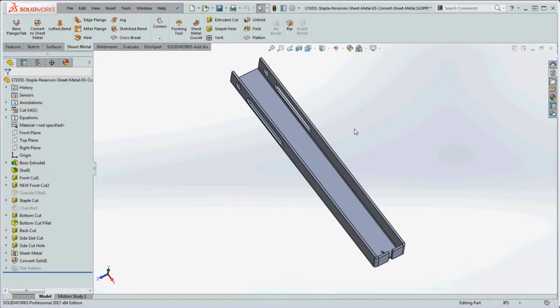You put your cuts, you cut it out, you put in your cuts for other items in here, and then you tell it where to bend and what the bend radius is going to be and everything else, and that's how you get your part. And the way you get that here in SolidWorks is you go over here to the bottom of the tree. There's a flat pattern folder in here.